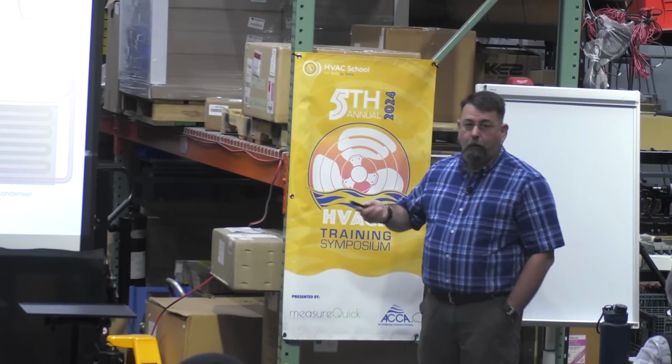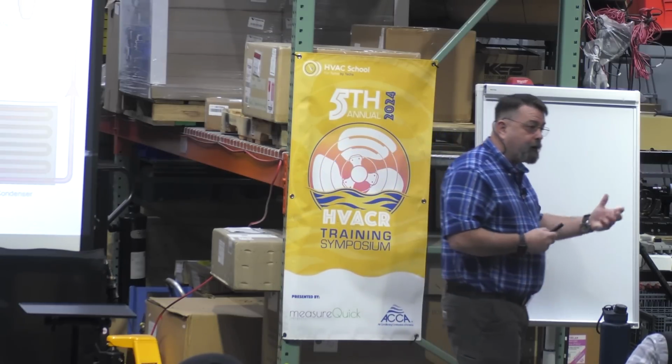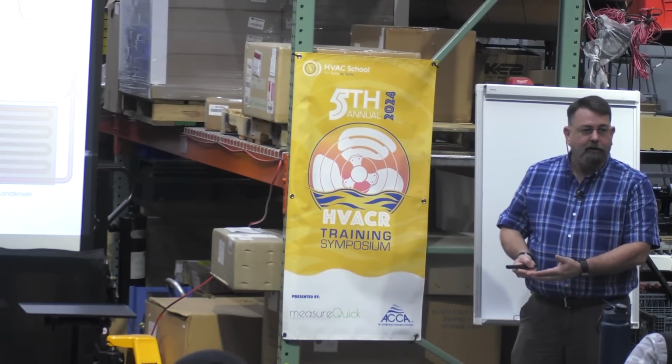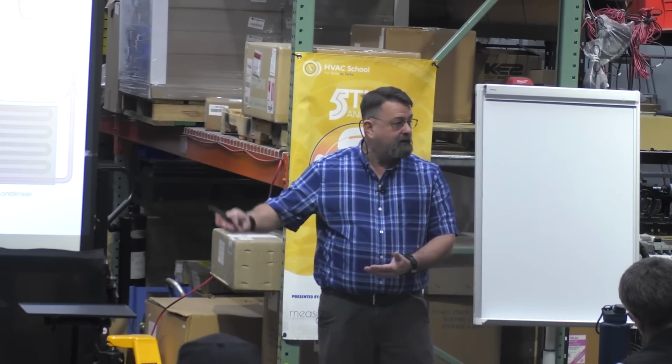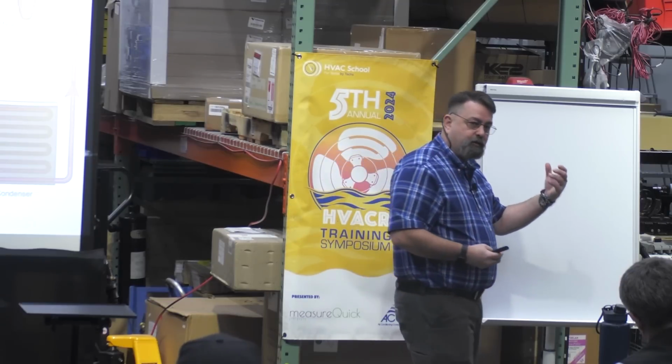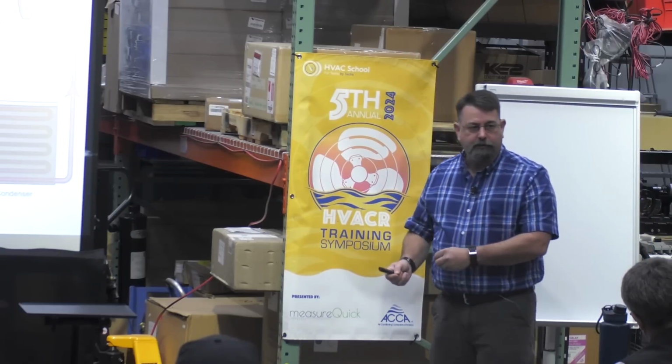The whole control, my thermostat, is not my case running warm. My thermostat is my suction pressure. Is it too high? Is it too low? I'm going to bring on things, compression, to maintain that suction pressure because of that PT relationship.